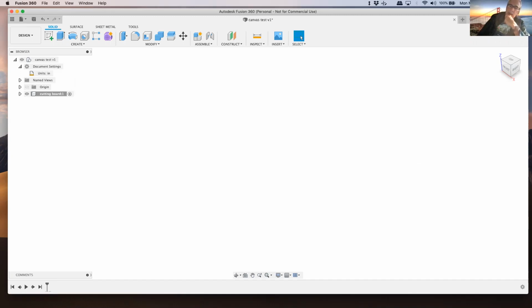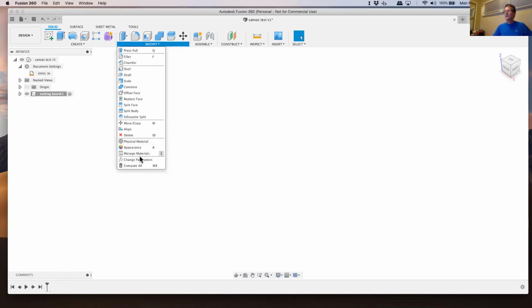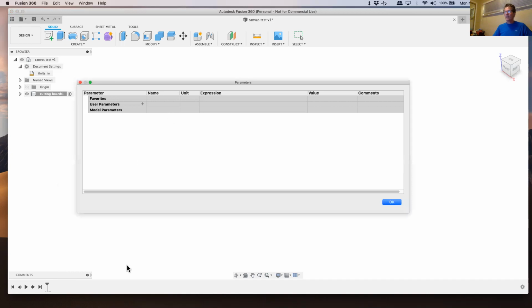I think I heard you say that going back in your timeline in Fusion 360 as a way of editing dimensions is kind of clunky. And I think what you were also saying was if you do have parameters set up, you just pop that up, make changes, and there's no going back in the timeline. Correct. So that's good clarification. Appreciate that, Travis. So what I was implying there is you can modify the parameters in the parameter table without having to figure out, in a fairly complicated product, which sketch way back there has the dimensions that you want to modify.